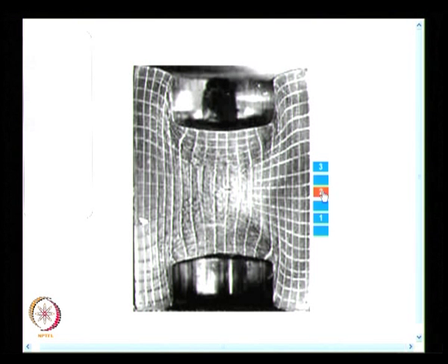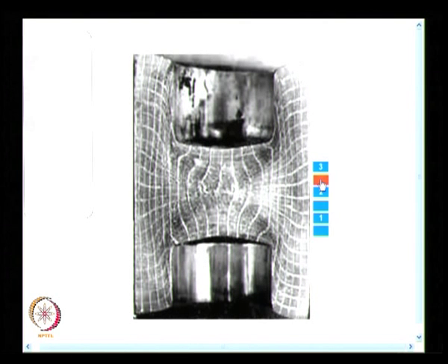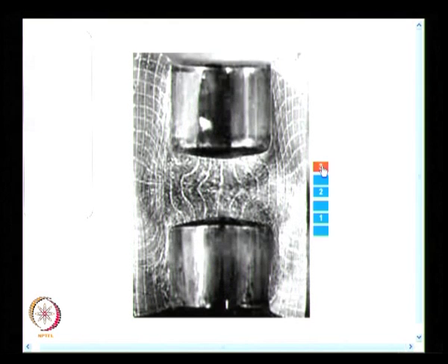So, I am really talking of a very high value of strain, and in this you do not require fine measurements, even these grids deform like this. So, you get very valuable information on the nature of strain field from this. You have very large plastic deformation, and for all those metal processing applications, people use the grid method, because that itself is sufficient to give you some information.